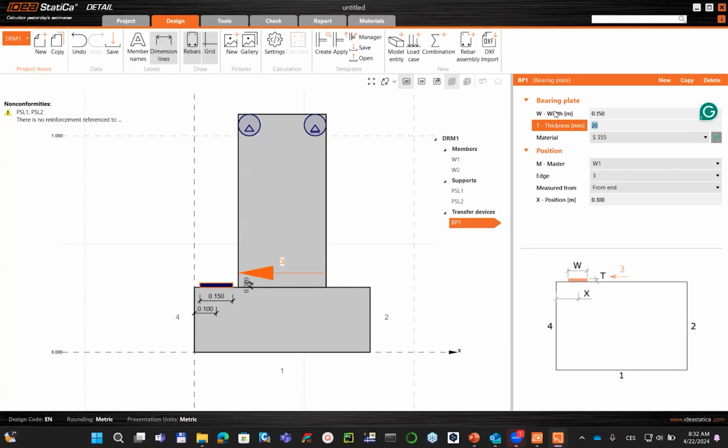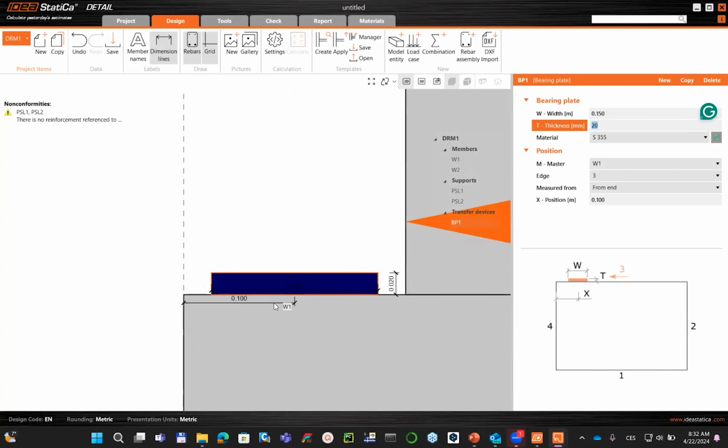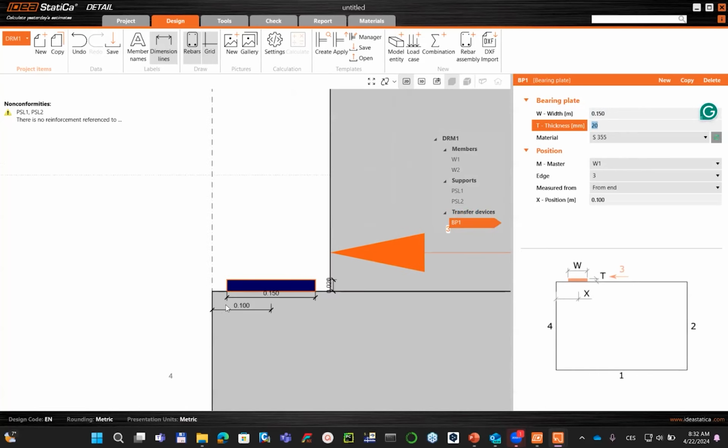The thickness is a very important parameter, because if it's really slender, there will be some local peak here. And if it's very thick, the redistribution of the force will be uniform. This is generally what I want. So you will use this thickness based on the real parameter of the plate that is there.